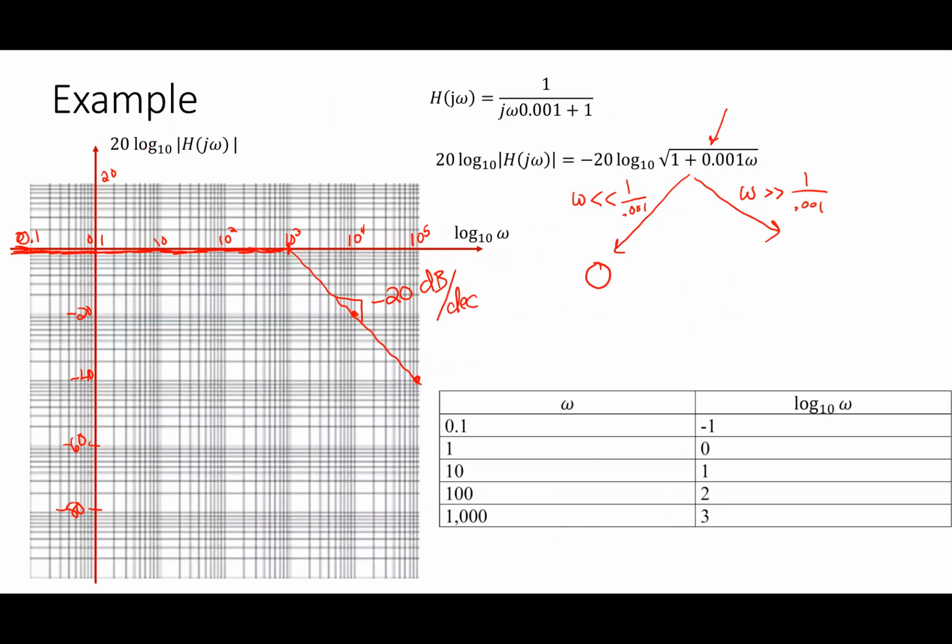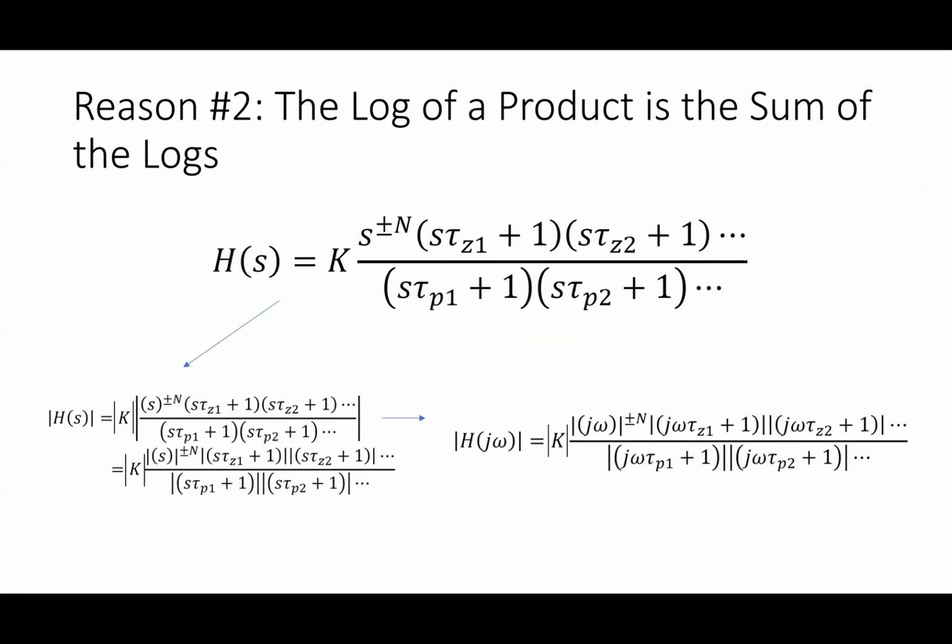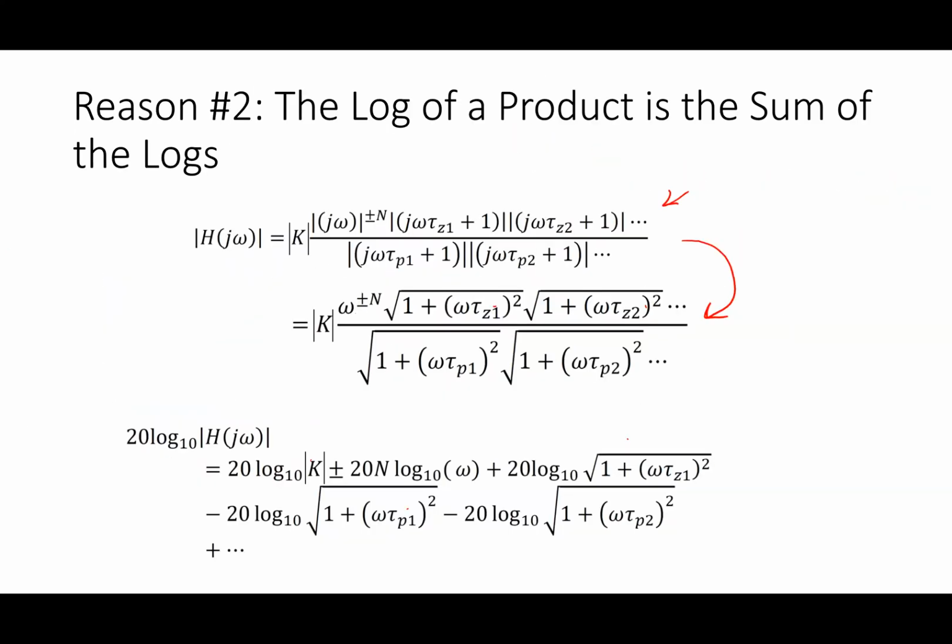If I know how to deal with one of them, I can deal with each one individually, and then I can just add them, right? So it's very easy for me to look at the result of a single pole or a single zero and just add them all up piece by piece by piece to create the whole diagram, okay? So the process becomes pretty straightforward, okay?